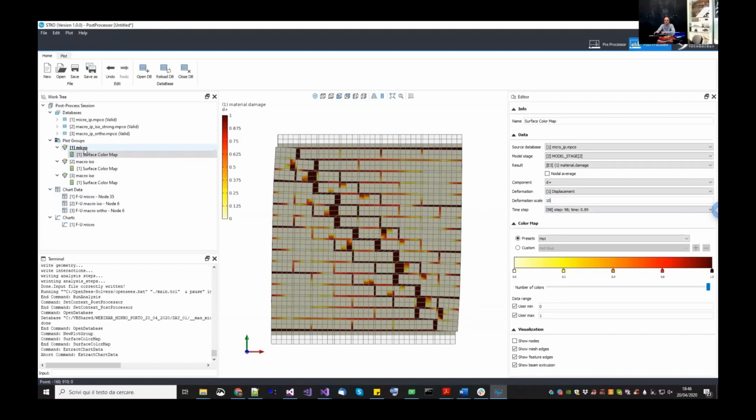For example, if we decrease the strength of the mortar in the mortar material properties, we can minimize the difference between the curve of the macro and micro, because as you mentioned, the initial stiffness loss is because of the cracks produced in the mortar joints.